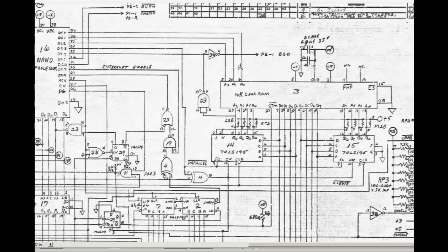It scans them out of sequence, and also it may repeat certain lines, and it does that so it can extend characters. It can print them at 1.5 times normal size, but it also allows it to have a couple of lines of pixels beneath the main body of the character for tails in Y's and G's, that sort of thing, or above the character. And it does make it look a bit confusing when you're trying to look at this on a logic analyzer, because the addresses don't appear in the sequence you might expect.